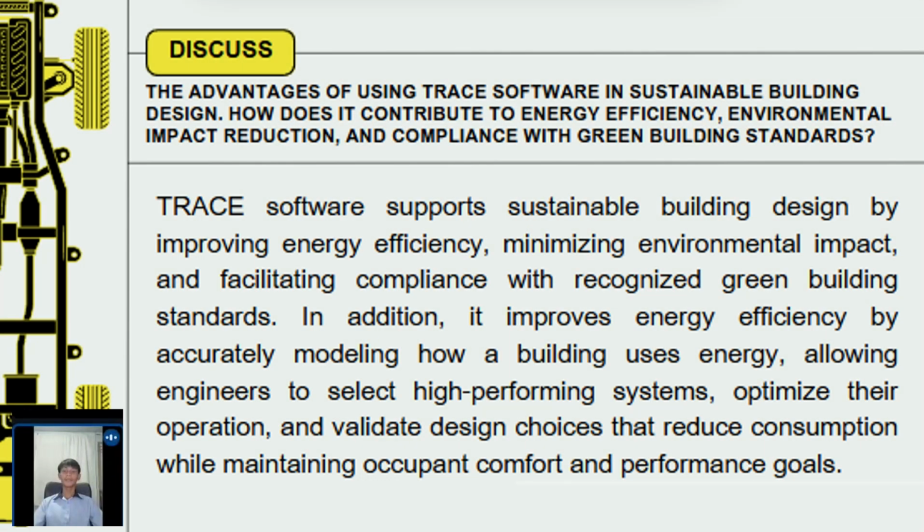What are the primary applications of Trace 700 and Trace 3D Plus in HVAC design and energy modeling, and how do they differ in their approach to system simulation? So Trace 700 is a traditional DOE-2 based software focused on 2D zone-based load calculations and lifecycle cost analysis. It is widely used for retrofit projects and straightforward system comparisons.